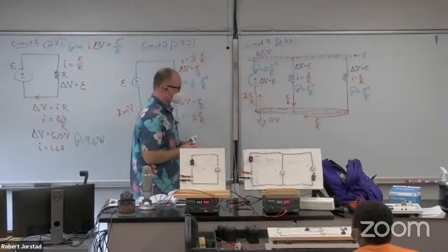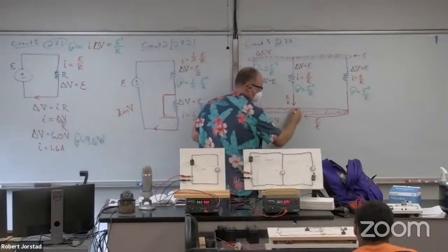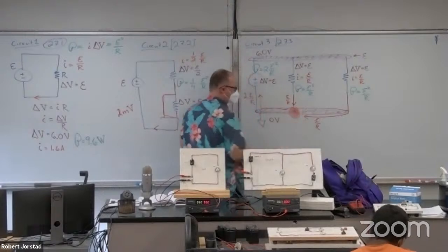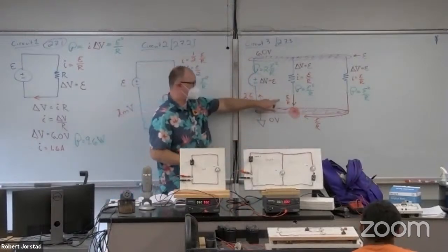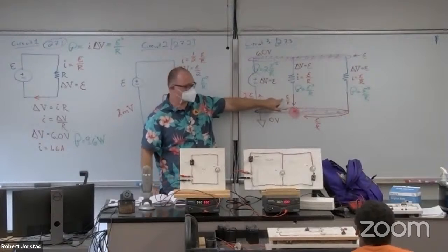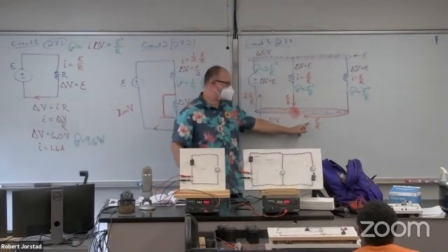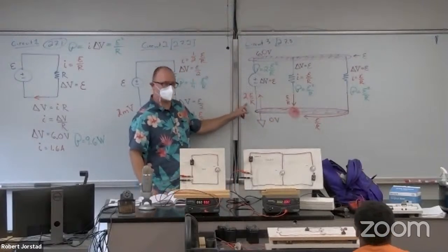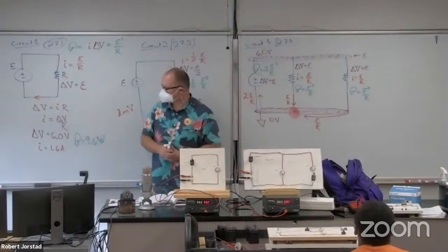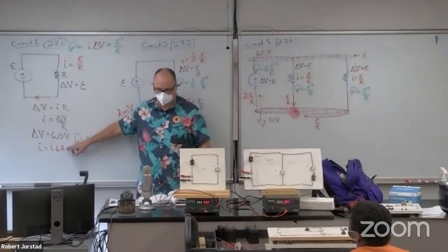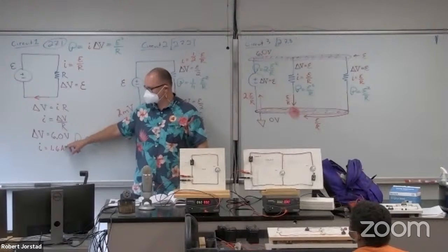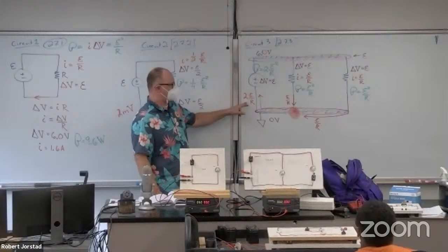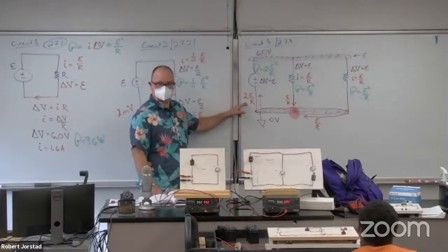The idea is at this spot right here, and I'm trying to draw it as a dot, I have 1.6 amps coming in from one light bulb, 1.6 from the other. That's going to spit out here. It should be about 3.2 amps, right? I'm just taking my reference number. We said the original circuit has about 1.6 amps, so I would expect to actually draw 3.2 amps.